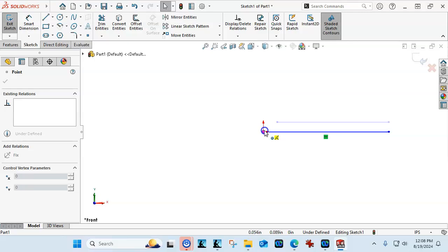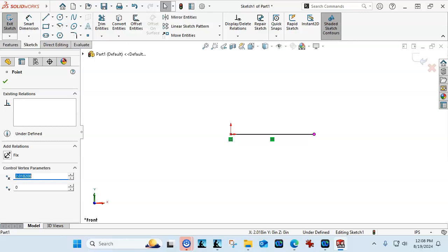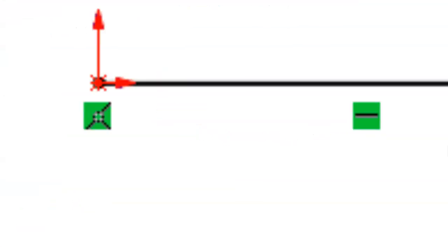and then I'm looking to do that little jump and get back to the yellow box that's telling me that I'm going to be coincident. The endpoint and the origin are now tied together. They have a relation, and I can see the coincidence and I can see the horizontal. So I'm going to shrink that up just a little bit, zoom in on it, and see if I can zoom in around those guys.